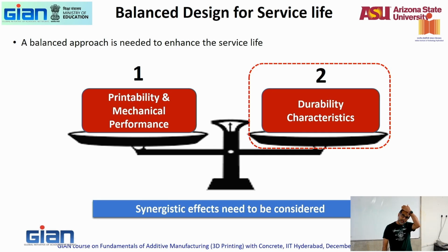Reinforcement corrosion. The reason that really bothers all of us is because reinforcing steel, when it corrodes, expands in volume. That volume expansion causes tensile stresses. Tensile stresses cause cracking. Eventually, the problem is cracking and the cracking induced ingress of deleterious ions and all of those things into your concrete. So that's where you don't want durability issues.